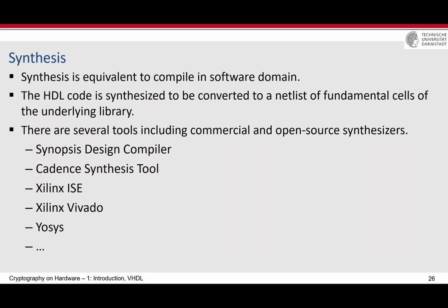But keep in mind the Xilinx synthesizers, or Xilinx tools, are just developed for FPGAs. That means you cannot use them for ASIC designs. You cannot just ask them, okay, then synthesize my VHDL or Verilog code for an ASIC, one particular library like TSMC 45 nanometer. This doesn't work. They work only by synthesizing the code that you have for FPGA, like the lookup tables and switch matrices and so on.